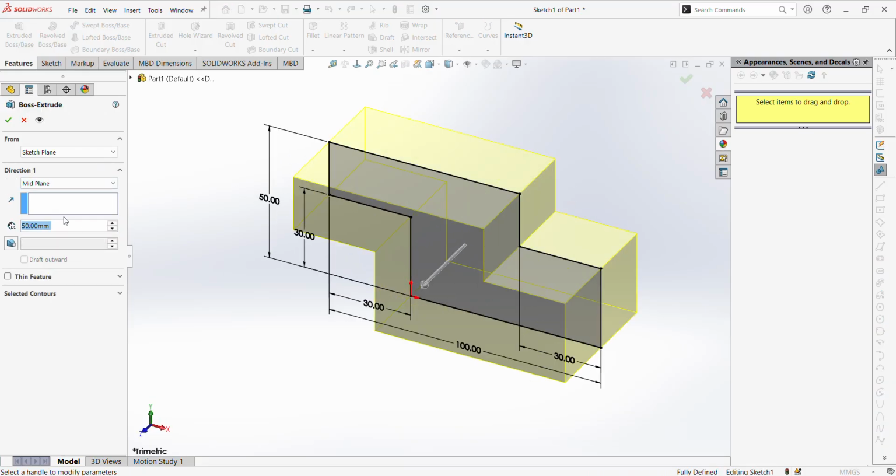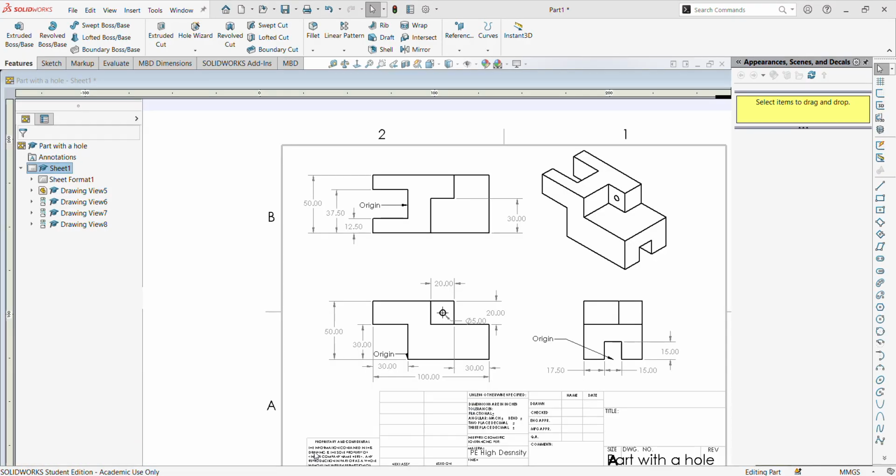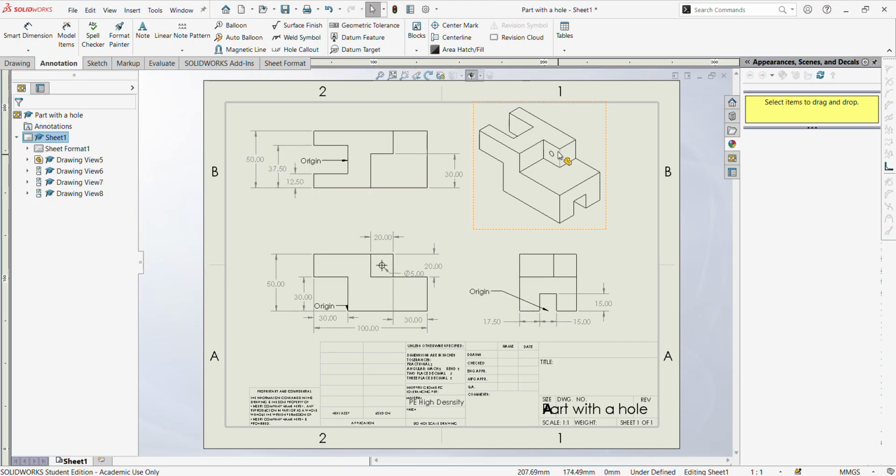Perfect. I think it was about 50 wide. Yeah, that looks about right in relation. Let's double check. Yeah. Okay. So we have our extrusion, we have our part now in 3D space, but we're missing some features. We're missing this cut here, this cut here, this cut here, and that cut there. 4 cuts, I believe. So let's talk about busting them out one at a time.